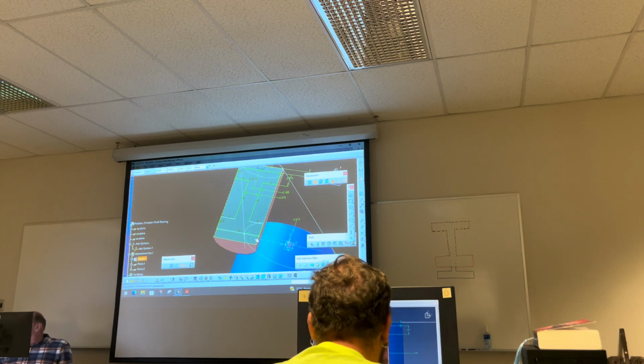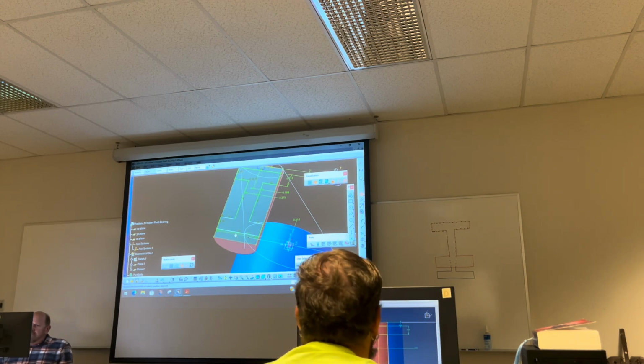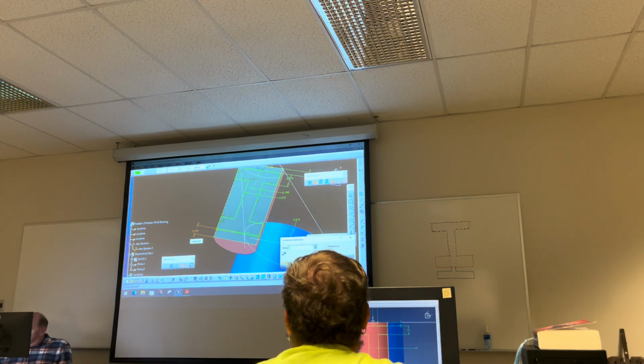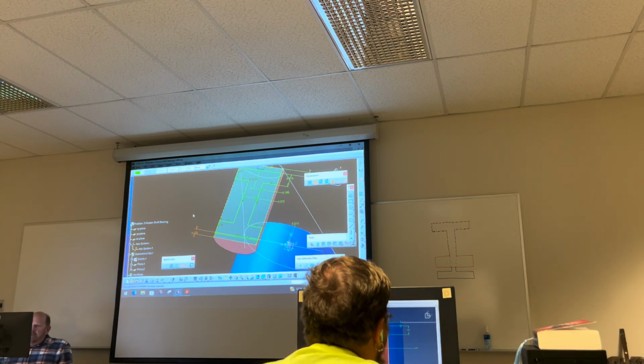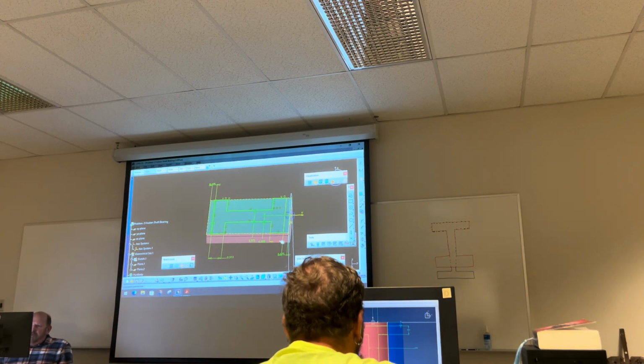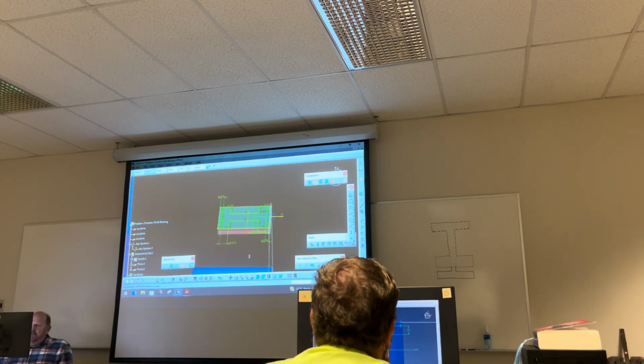And the bottom one is 1/8 of an inch as well. So I'll go from this line to this line now, and that one will be 0.125. Everything else is maintained. I got the 0.313 here, the 0.313, and then the center is 3/8.